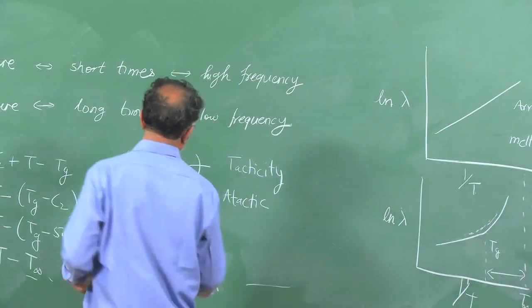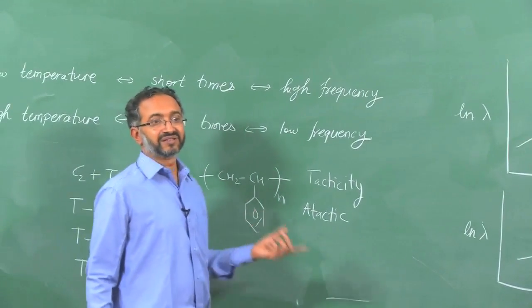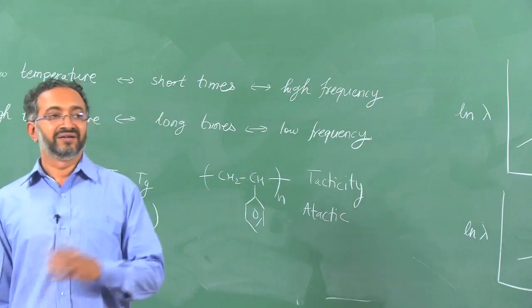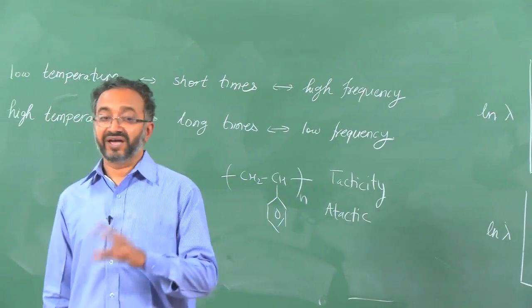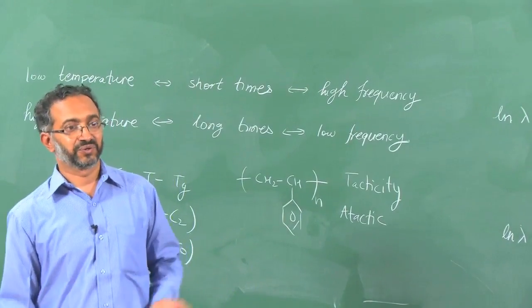If you get a material which is isotactic, where there is a well defined position of these groups, then you can get crystallization. And then what he said was true, that depending on the cooling rate you can manipulate the crystallinity just like metals and alloys and so on.